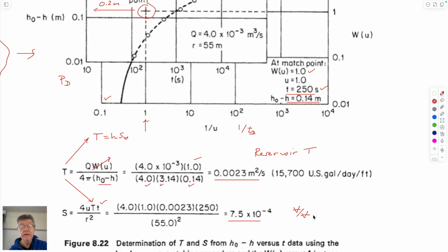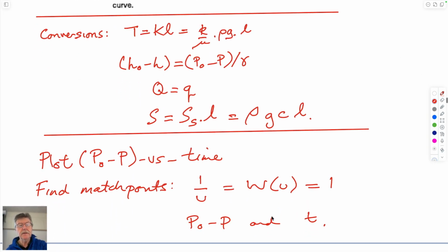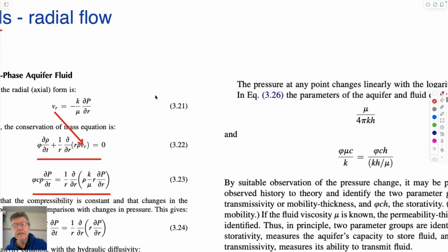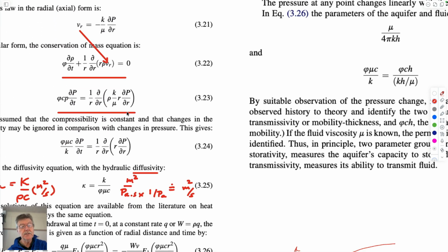So it's a change in volume per unit volume for a change in elevation head within the system. And so perhaps that's a bit confusing, because we've used two systems. But the main point to get is that we end up with a conservation equation with Darcy's law in it.